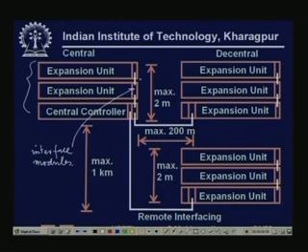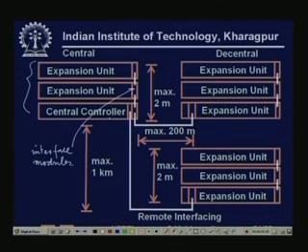Similarly, you can expand your number of modules. Sometimes you can put your modules in a different almirah, which is a different cabinet. When I say almirah, actually it's a cabinet. For that you need a special interface unit. For reliable data transmission, such distance requirements are there at a certain rate, so you can go up to something like 100 meters, which is a lot.